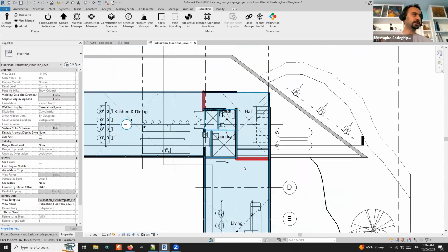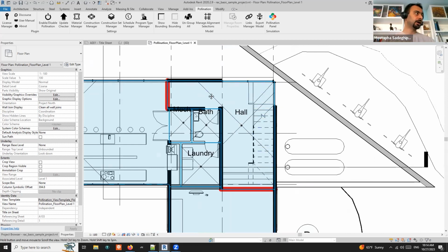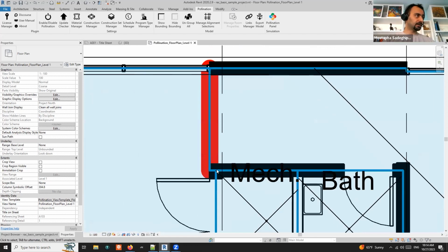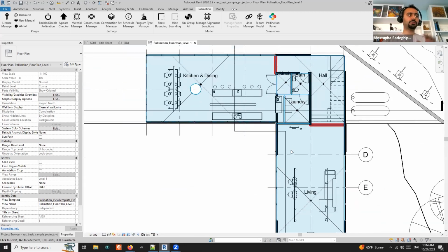So you get a lot of issues, like a lot of small edges. You see a lot of models that have a separation line right behind the window, which, if you use the full model, then the window won't show up. We will see that when we go to the second floor. There are cases like this with small edges. If you want to fix them, you can go fix them. For this floor, all the rooms are okay, and these separation lines are fine.